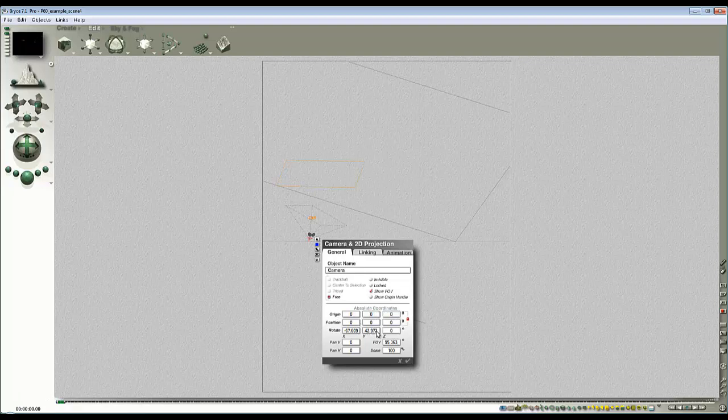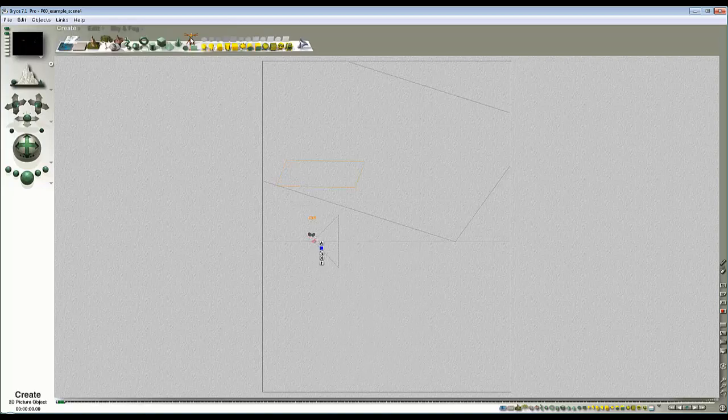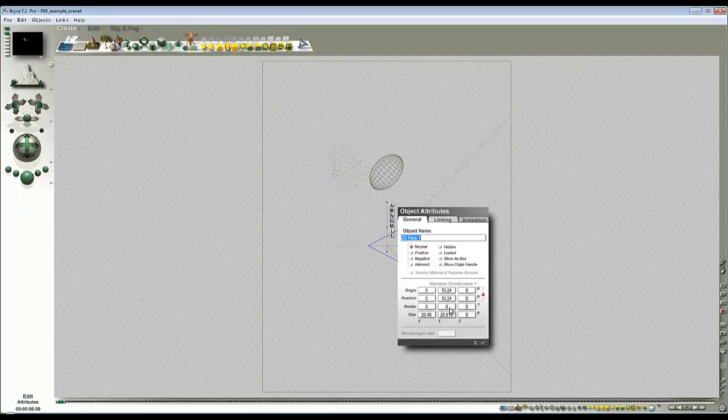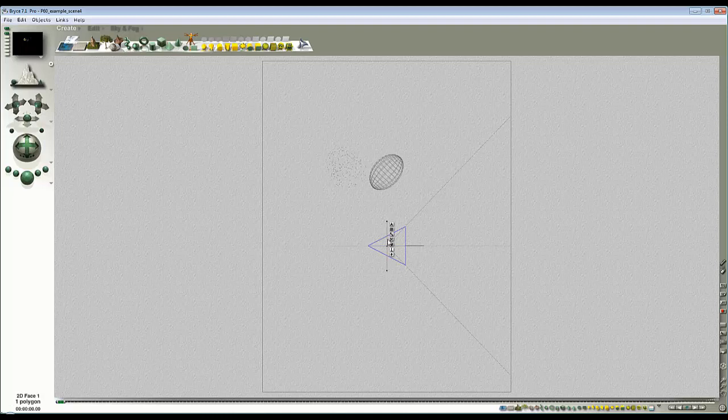Set all these to 0. Down here, just go to the create shelf, click on the little gold man, navigate to my backdrop. Okay, check out of that, zoom in a bit so I can see what I'm doing, modify the attributes for this so that it's on the ground, and then move it along the z-axis. Let's see, obviously I was in object space there, or world space, so that's going to go behind the asteroid and hopefully not interfere with anything else.